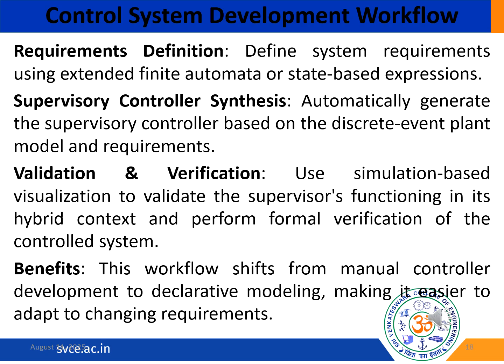So moving on to supervisory controller synthesis. It automatically generates the supervisory controller based on the discrete event plant model and requirements. So a supervisor is synthesized for a system consisting of two multi-movers.